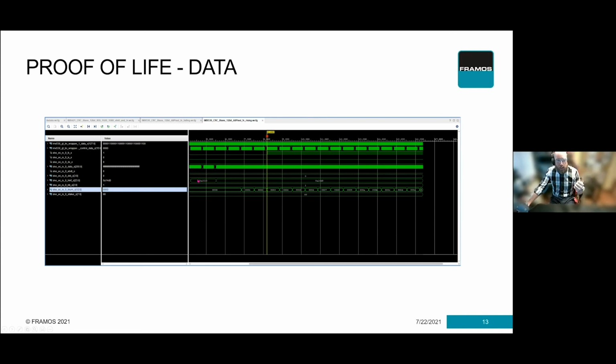So we can actually, just by looking at all the data as it comes out of the receiver side of the transceivers of the FPGA, if we have a look at the data there, we can then see, is everything in sync? Is everything correct? We can look for flipped bits. We can do lots of different little options.